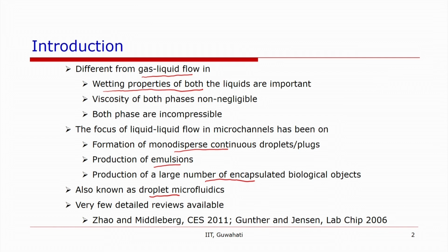In addition, say for heat transfer, gas-liquid flow in the Taylor flow regime has been used. Why? Because the internal recirculations in the liquid slug enhance the mixing and thereby the heat transfer, on a Nusselt number basis. However, in gas-liquid flow, the gas bubbles have very low thermal mass, very low m Cp or rho Cp value.